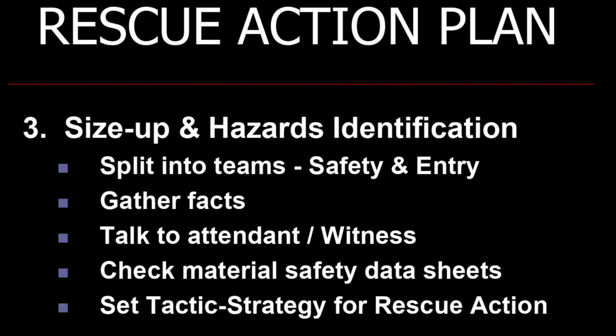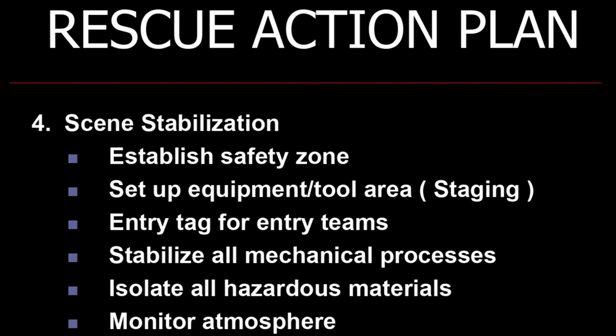3. Size up: hazards identification, split into teams, safety entry, gather facts, talk to attendant witness, check material safety data sheets, set tactic strategy for rescue action. 4. Scene stabilization: establish safety zone, set up equipment tool area, staging, entry tag for entry teams, stabilize all mechanical processes, isolate all hazardous materials, monitor atmosphere.